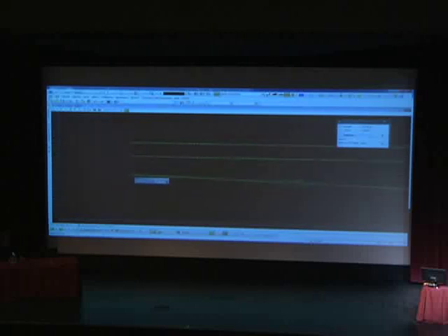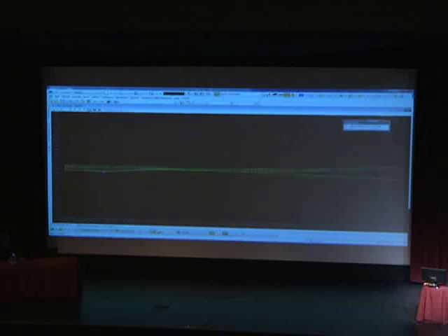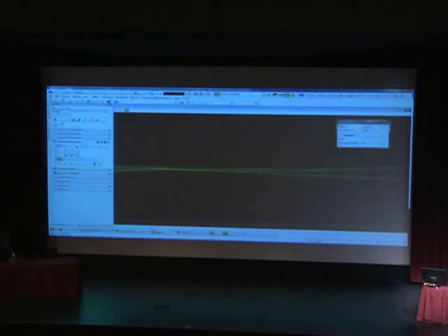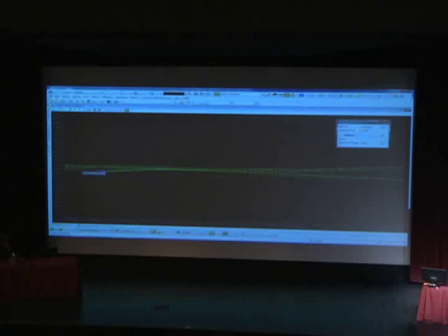So then what I did was I selected the feature definition, grade ditch bottom. That's very important. This is the feature definition I selected. And I clicked that chain on the top right-hand corner over there. It's kind of a little difficult to see. What that little chain does is it allows me to easily draw my line nonstop all the way through. I just snapped to locations where I thought my ditch line should be, and everything looked like it was underneath the edge of pavement, and it was fine.